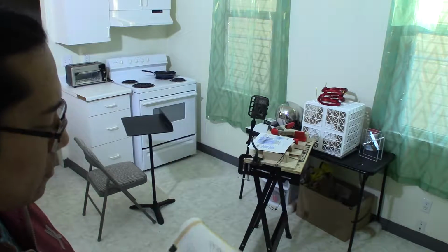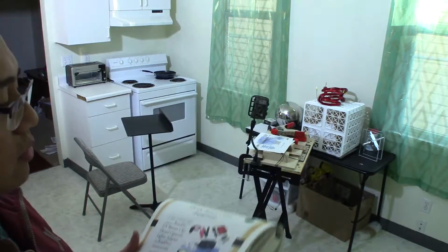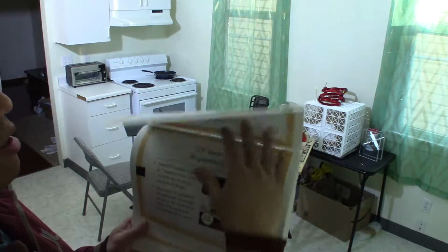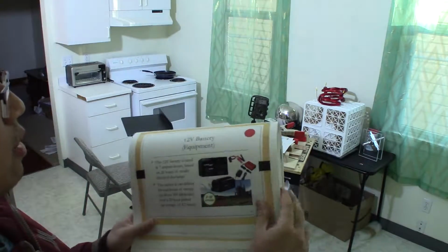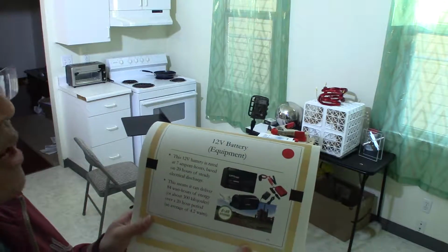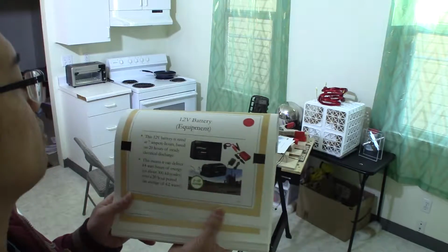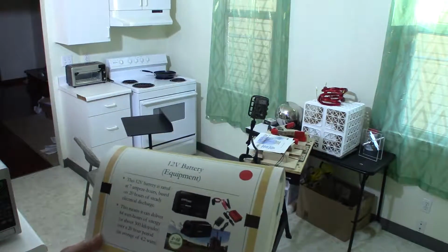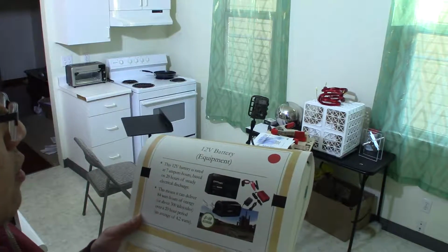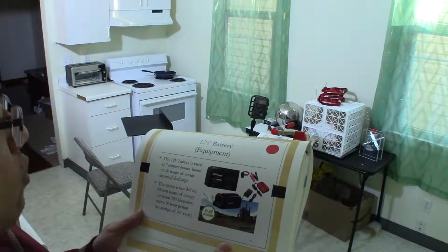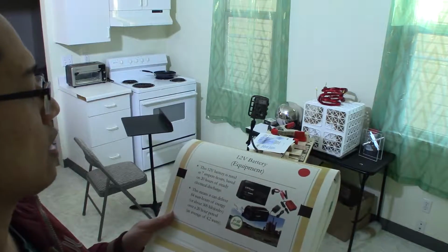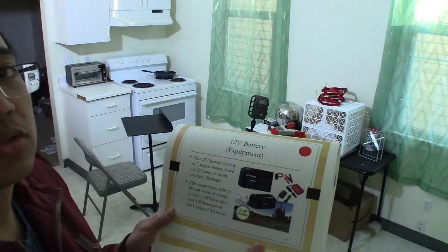So I had the clips and everything. I had to attach a 12 volt battery, and so on and so forth. So basically, this 12 volt battery is rated at 7 ampere hours based upon 20 hours of steady electrical discharge. Okay. This means it can deliver 84 watt hours of energy, or about 300 kilojoules, or over a 20-hour period, an average of 4.2 watts.